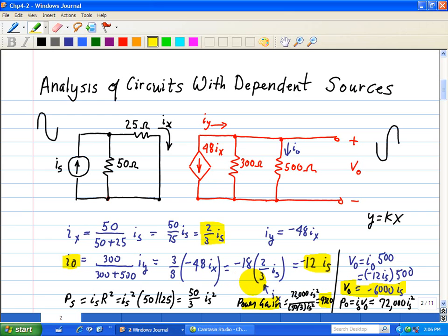That is, the external power supply is not shown in the circuit diagrams, but it's implicit when we do these types of calculations. So when using a dependent source to model an active circuit, we assume that the external supply and the active device itself can handle whatever power is required by the circuit. So when designing the actual circuit, the engineer must be certain that the active device and its power supply operate within their power ratings.